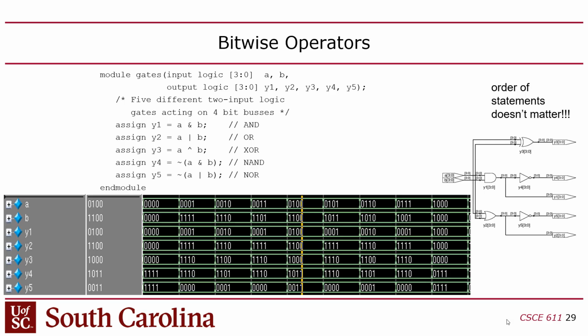And inclusively, 3 down to 0 is 4, right? So if you want to declare a signal with n bits, you have to say [n-1:0], right? I don't know why they force you to do the :0 here, because as it turns out, you could also put [0:3] and it makes no difference at all. It's not like it reverses the bits or anything like that, right? Or at least when you declare it, right? So that's how you declare a multi-bit signal.